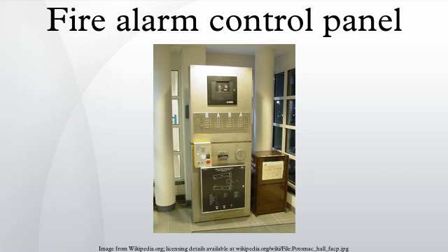A conventional fire alarm control panel employs one or more circuits, connected to sensors wired in parallel. These sensors are devised to dramatically decrease the circuit resistance when the environmental influence on any sensor exceeds a predetermined threshold. In a conventional fire alarm system, the information density is limited to the number of such circuits used. To facilitate location and control of fire within a building, the structure is subdivided into definite areas or zones. Floors of a multi-story building are one type of zone boundary.